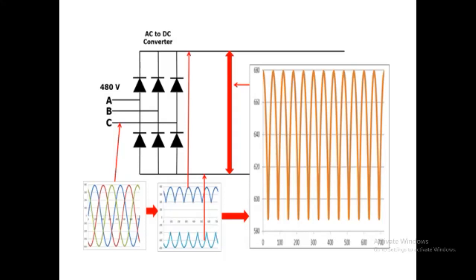Now we can get rid of the AC ripple on the DC bus by adding a capacitor, and a capacitor operates in a similar fashion to a reservoir or accumulator in a plumbing system. This capacitor absorbs the AC ripple and delivers a smooth DC voltage. This is the simple construction and working of a simple VFD system.